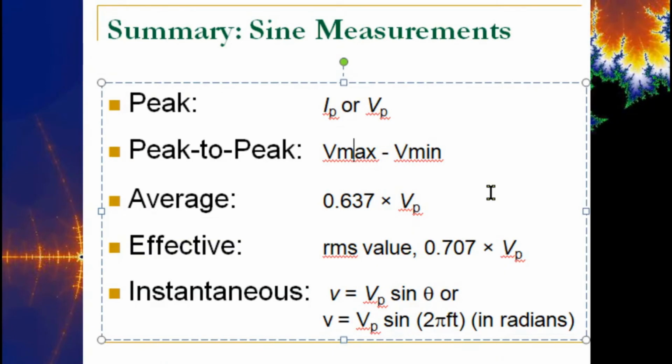So if you were going to measure, let's say you wanted to see if one of your breakers was working in your panel, in your garage or whatever, and you take your $10 Menards meter that has no protections in it at all, and you put that thing up there to measure the voltage, and the power company has a surge on the line, that thing might make it to your meter. If that thing makes it to your meter, it will explode and arc flash and burn you with third-degree burns in your face, okay? So on your meter, there's a CAT rating, a category rating, all right? I'm going to go over here and look at our Mastech because I forget what this one is.